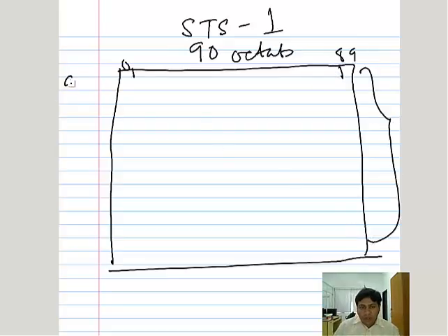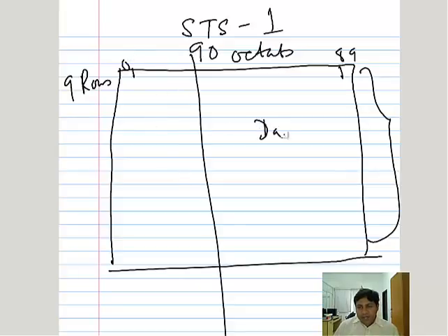Each and every row defines something. There are two parts: one is called overhead and the other is data. In that, the first three octets, 0, 1 and 2, are basically my header section.